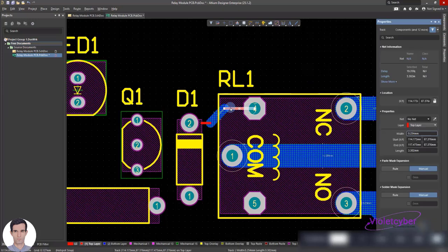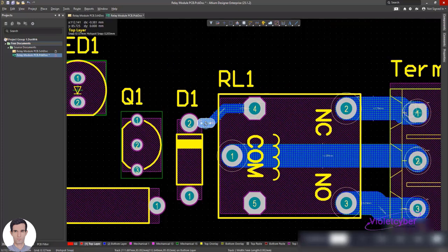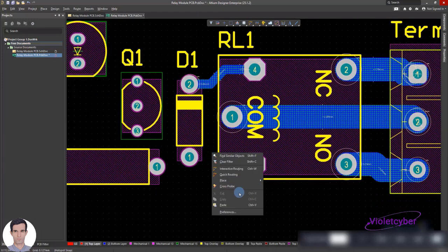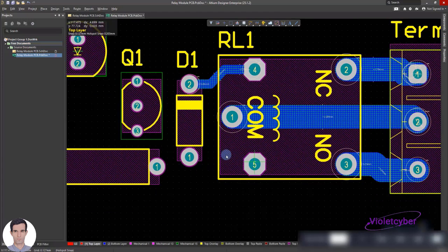You see, I put the pins and their connections at 1 millimeter, and I choose the bottom layer because my circuit is deep, and it must be a bottom layer. Well, this is the connection of the first pin to the diode, and I do the same with the second leg. If at some point you make a mistake while drawing the path, for example, you can easily select that piece or that path and start over from the beginning. There is no problem with that at all. 1 millimeter in bottom layer.